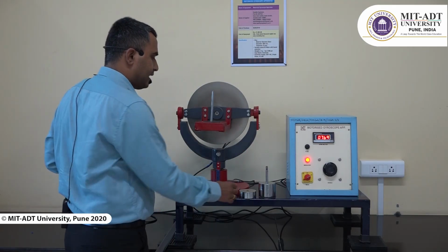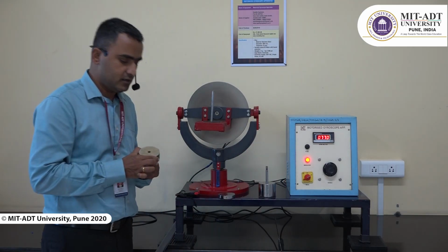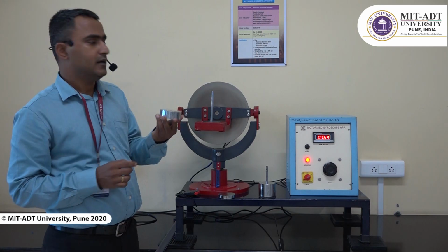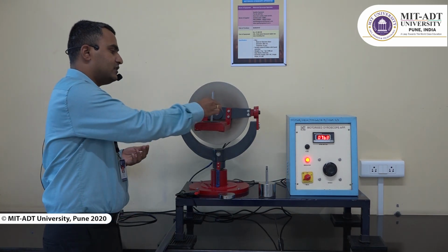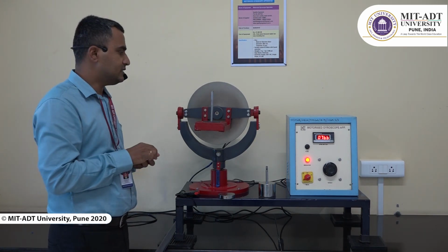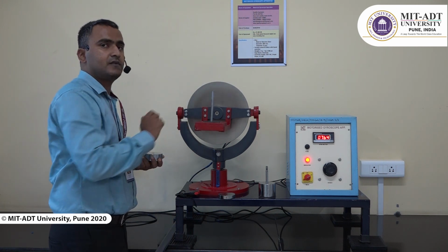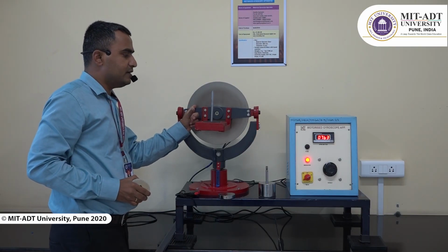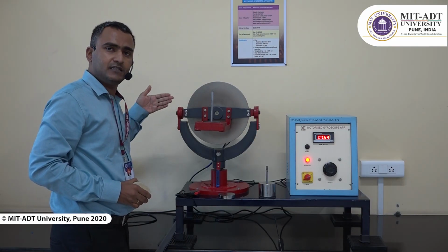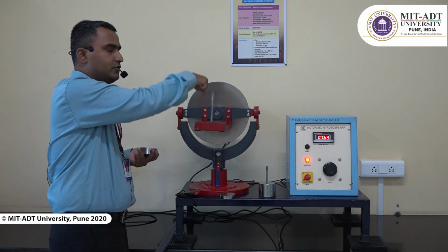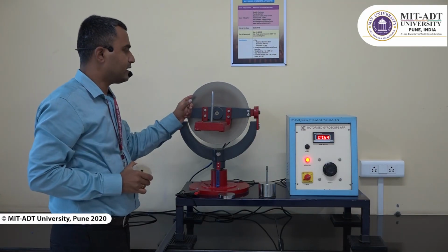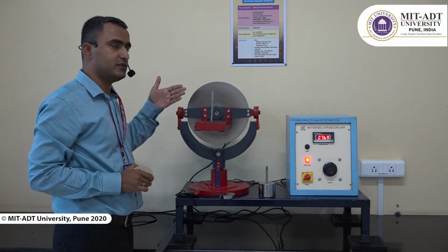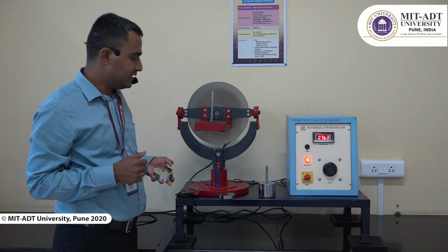Now how am I going to measure the applied torque? That is as simple as that. We used 1 kg of mass and we kept it on this platform. That means we are using a mass which is moving downward, which is 200 millimeter away from the mid plane of the disk. So we know what amount of force is acting downward. We know at what distance it is acting from the mid plane of the disk. So we can easily find out what exactly is the applied torque.